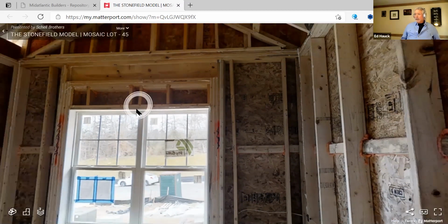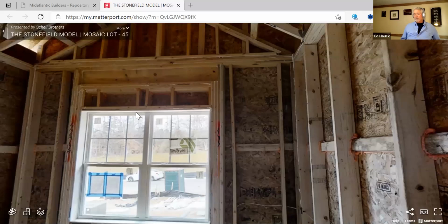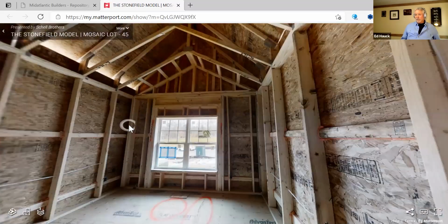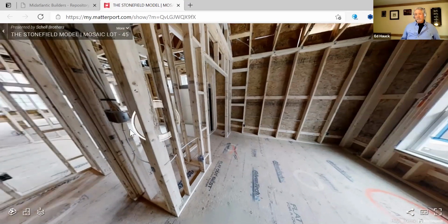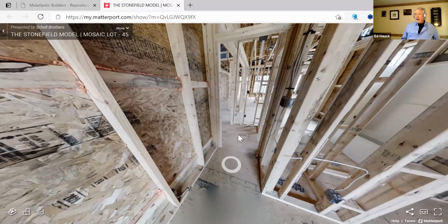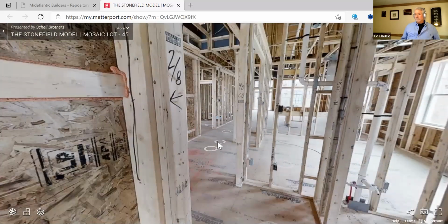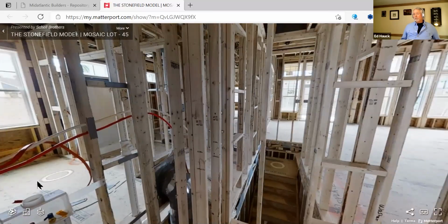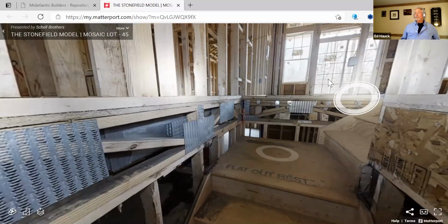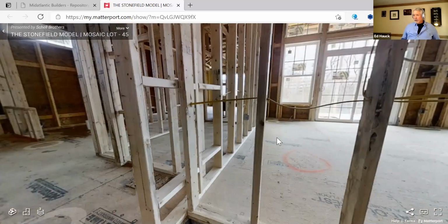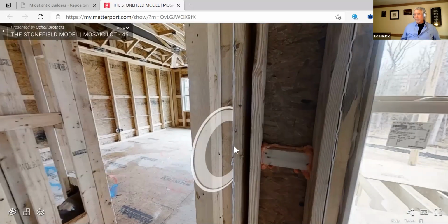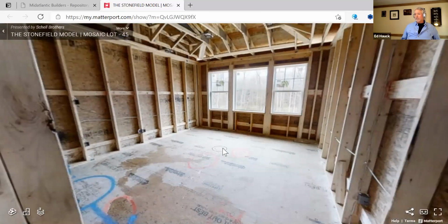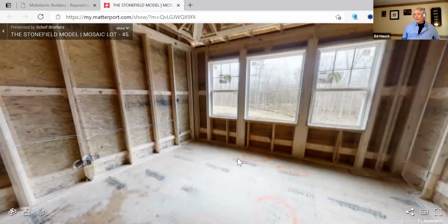And like I said, a year ago, nobody cared about this. You know, when a stud was $3.50 a stud, we were just blowing and going. Now it matters. Yeah, I'd say without 2-foot on centers as part of it, on interior non-bearing, you have 100 to maybe 125 studs or more in this house that are extra, maybe more.